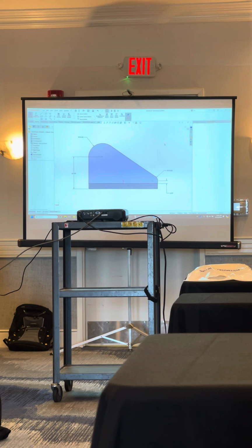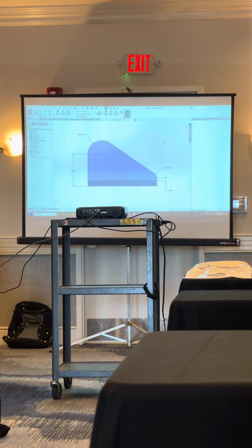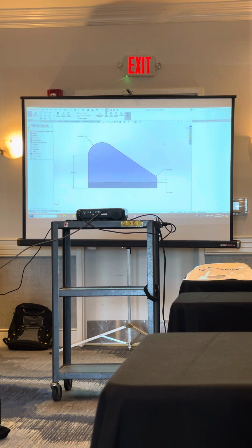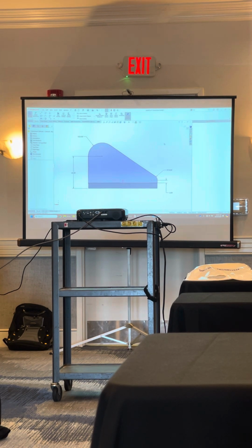So we don't have a tool that does it. Autodesk Inventor, apparently, has a function that you can click and it auto moves the stuff on the screen. And I'm always like, I kind of want that functionality. But the last phase after you test the geometry is then to put the dimensions on. What this really gets away from is that if you don't test the geometry, you may be missing a relationship. Even though that arc and line look like they're tangent, they're not tangent, right?